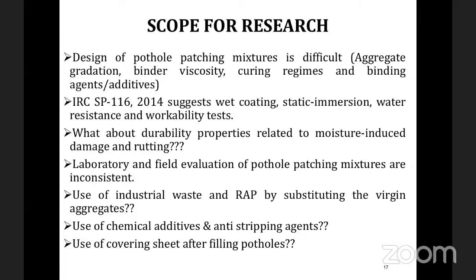There are a lot of anti-stripping agents. Anti-stripping agents lower the moisture damage, and there are some chemical additives which will improve the rutting properties. So you identify some additives and agents, mix them with the normal conventional aggregates, and assess the properties.